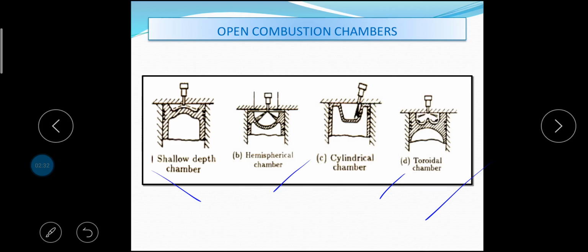This design was attempted in recent diesel engines. This is a modification of the cylindrical chamber in the form of a truncated cone with a base angle of 30 degree. The swirl was produced by masking the valve for nearly 180 degree of circumference.